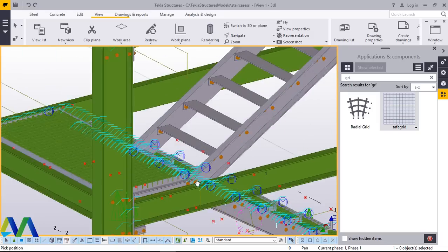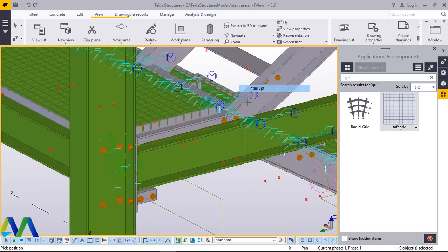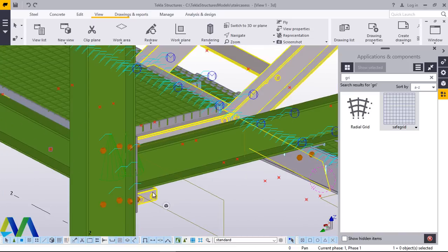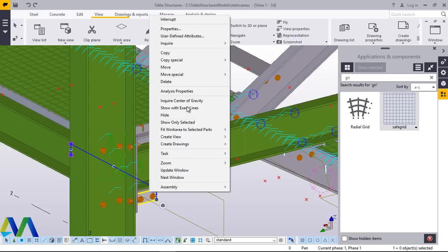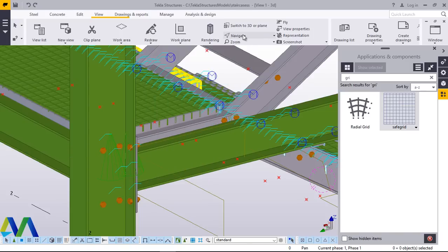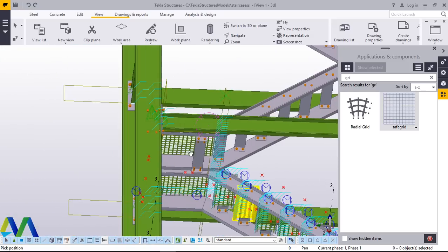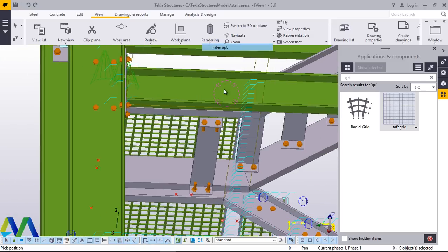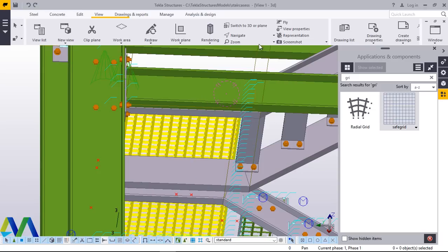And the threads on top here. Now I'll come here, click on that, right click and explode that. Now I'll be able to delete individually all those members. Come to navigate, click on this and turn it round. Right click, pick that, right click and delete that.